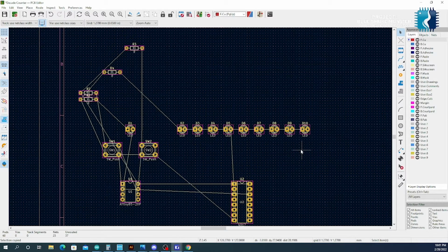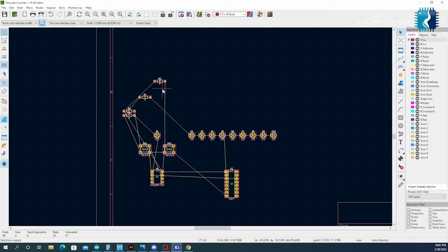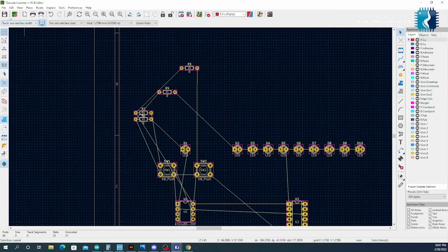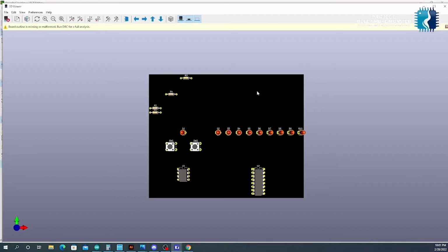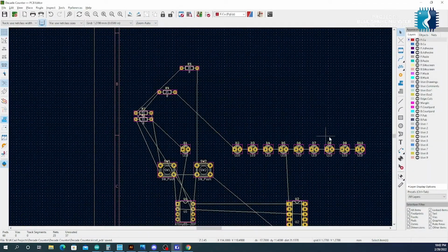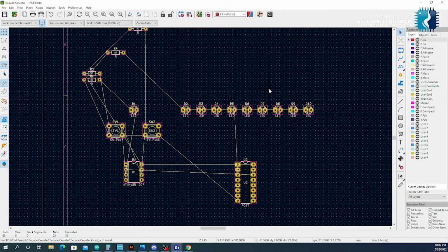Yeah, that worked nicely. Question is, what does footprint annotation do? Basically, it's going through a numbering, so it's creating a unique number for each, which just so happens to have aligned now with what they were called on the board. So that did most of the work for me. In fact, if I hit save and I try to render this board, look at that. That's beautiful. That's cool. Not bad. So we can start zooming in a little bit on some trace routing and other stuff.